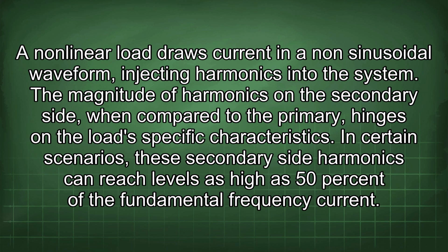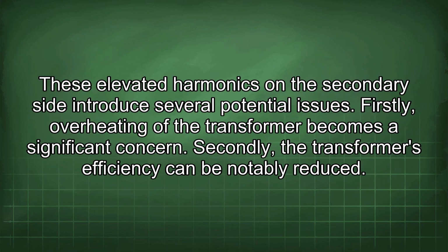A nonlinear load draws current in a non-sinusoidal waveform, injecting harmonics into the system. The magnitude of harmonics on the secondary side, when compared to the primary, hinges on the load's specific characteristics. In certain scenarios, these secondary side harmonics can reach levels as high as 50% of the fundamental frequency current. These elevated harmonics on the secondary side introduce several potential issues.